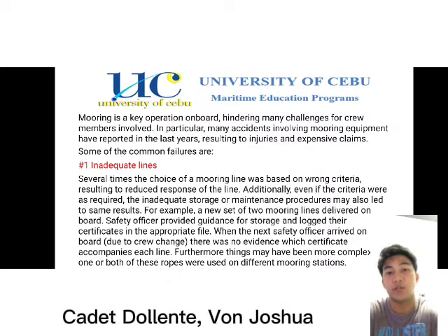Mooring is an operation on board presenting many challenges for the crew members involved. In particular, many accidents involving mooring equipment have been reported in the last year, resulting in injuries and expensive claims. Some of the common failures are, first, inadequate lines. Several times the choice of mooring line was based on wrong criteria, resulting in reduced response of the line. Additionally, even if the criteria were as required, inadequate storage or maintenance procedures may also lead to the same result. So, for example,